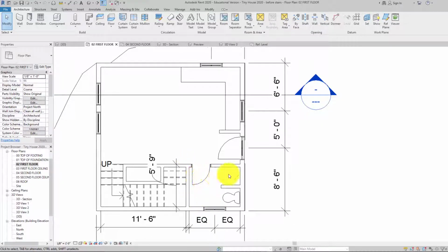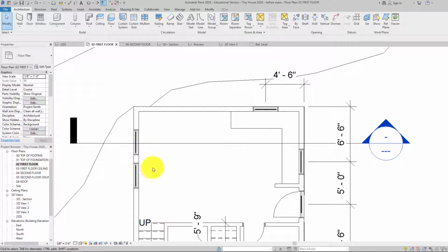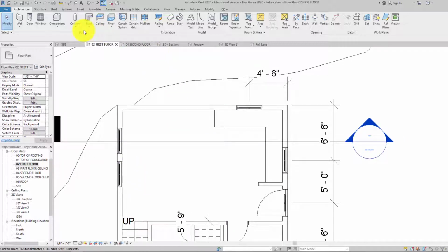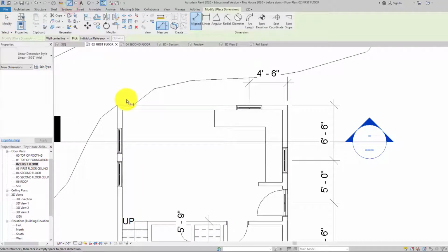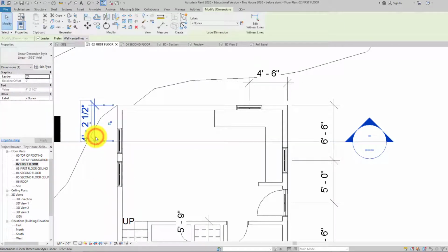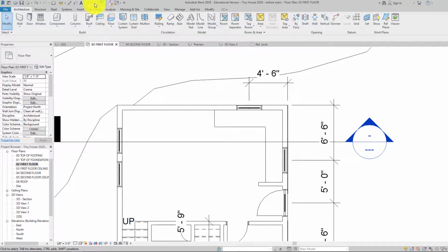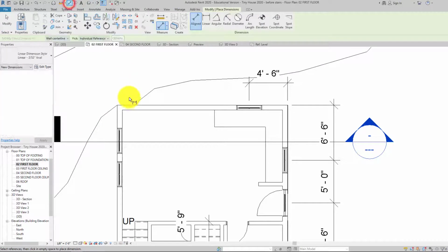So okay, that was for this area right here, and now let's just put these windows kind of where we want them, and I want them to match my upper floor exactly. So I'm gonna hit tab, grab that, and then this. Oops, see, I clicked one too many times. I want these to be tied together, so I'm gonna do that again. Grab my align dimension, hit tab, click the middle, and then click this middle.